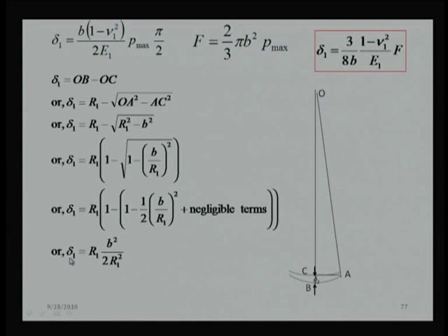So, if we can simply find out the deflection in terms of the force, or the contact patch in terms of the force, that is very clear from this relation. I can find out either delta or B, it will not be much problem. There are two equations, two variables, both will give a straightforward relation to us. So, here B cubed is given as 0.75 R1, the elastic properties, into F.